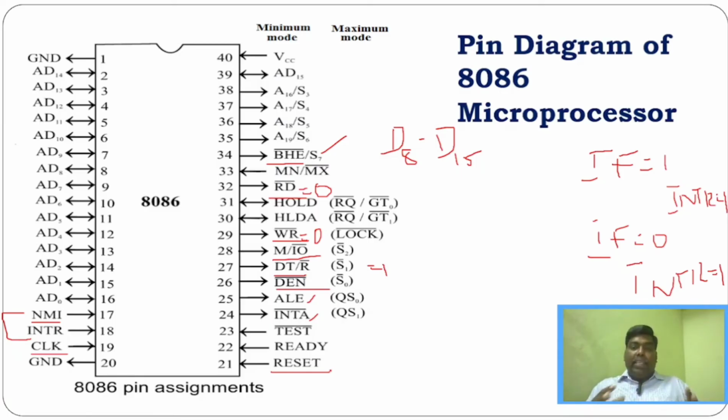That is a complete reset. But to reset the microprocessor, this signal has to be enabled for at least 4 clock cycles. Only then will the microprocessor go to the reset mode. And the READY signal is for when we want to connect an external peripheral device. The microprocessor works at a greater speed, but the peripheral device which we connect might be slower.